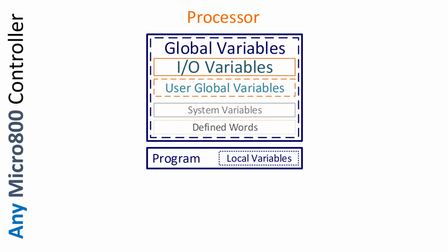Let's focus in on the interaction between code and the program file and these various locations of data, these various areas of memory. Let's assume that we have downloaded a project into the processor's RAM. Remember that the processor is a separate section of the electronics in the controller. So if you say controller and processor interchangeably, you can get away with that. It's always a good idea, when you're referring to the electronics that does the processing, that has the RAM in it, to call it the processor. If you say in the controller, it's just assumed you mean the processor RAM.